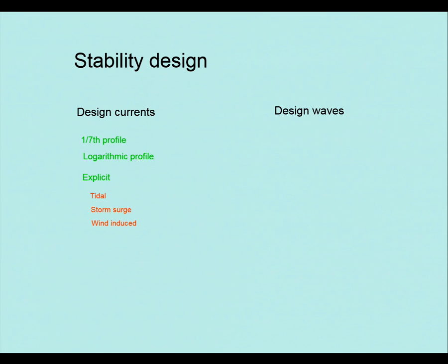So if you've done wave theory and tides and movements, design wave definition, significant wave. A pipeline we design is a long, slender structure, so we take the significant wave and not the maximum wave. If it was just a piece of cross member on the base of a platform, we apply the maximum wave to that. But with a long, slender pipe, we're allowing for the pipe to try to be moved at a small area, and it wants to resist it in other areas. So we use this significant wave.